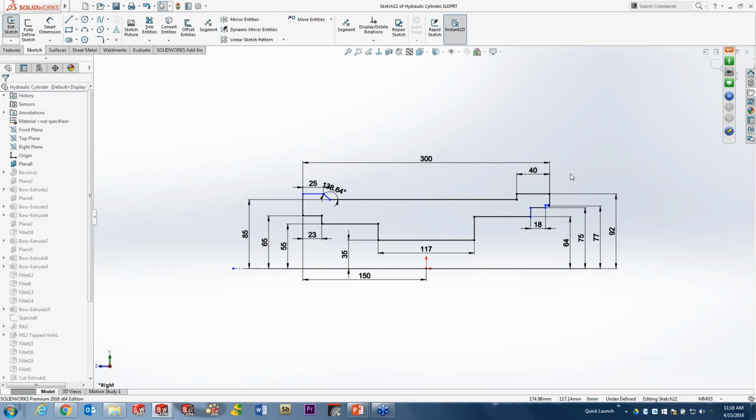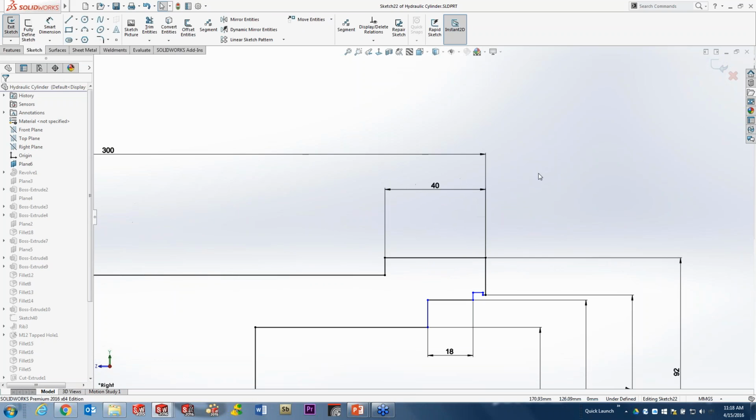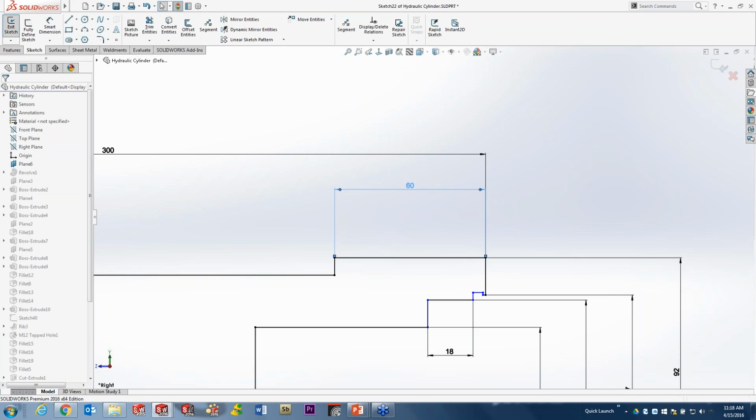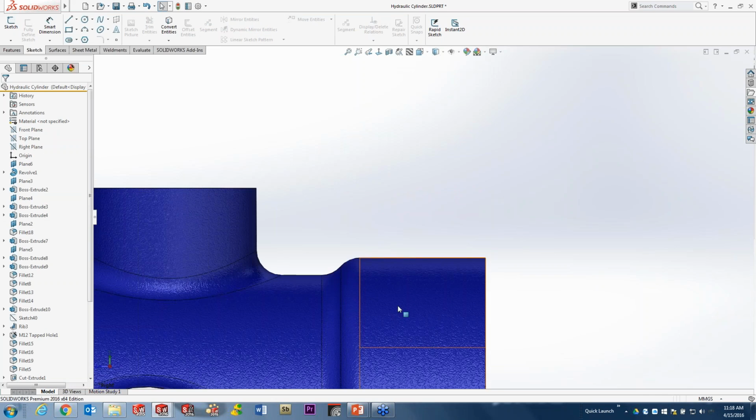Typically a dimensional edit, whether you're in the sketch or double-clicking parts in solid mode and then editing those dimensions, requires about a 5-click operation. Typically what happens here is you would double-click a dimension, 2 clicks there, change the value, and either hit rebuild now and exit or hit exit and then rebuild. Either way, that's a lot of clicks that we've got to deal with.